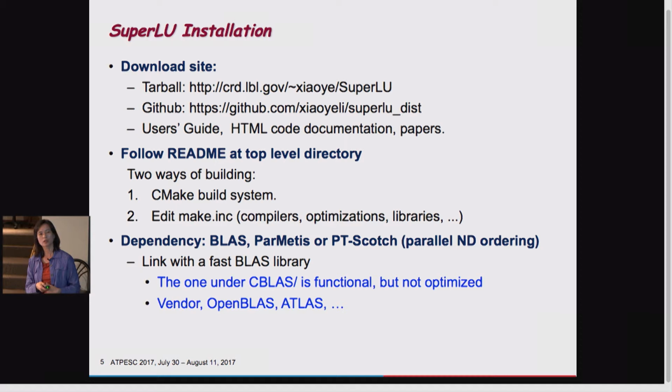Or you can use the open source libraries called OpenBLAS or Atlas. So you can Google those. So that's critical for performance. The reason is that even though the global matrix is sparse, internally we look at dense blocks and we try to apply BLAS operation GEMM, level 3 BLAS, on those dense blocks.